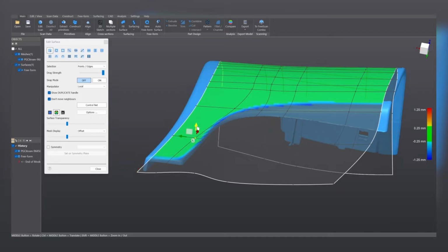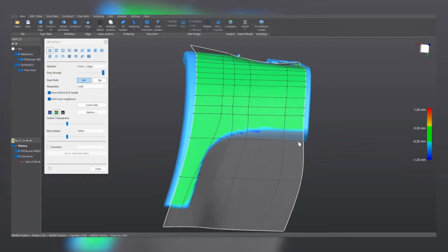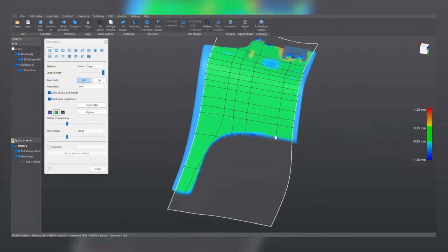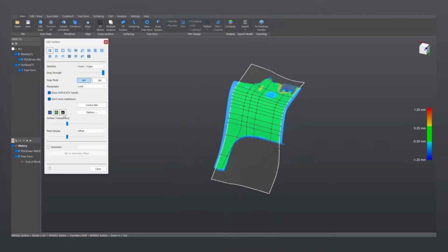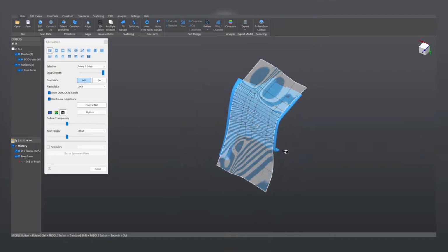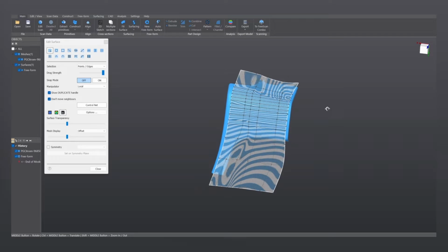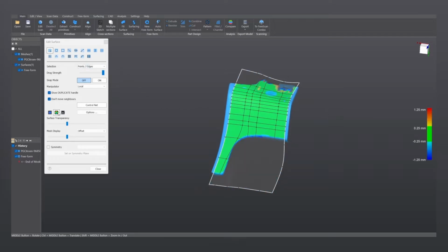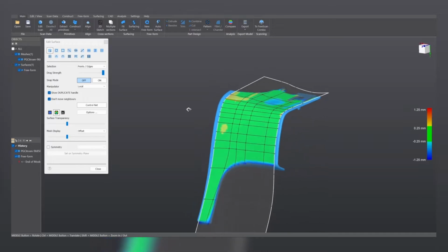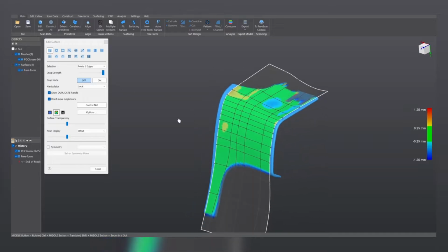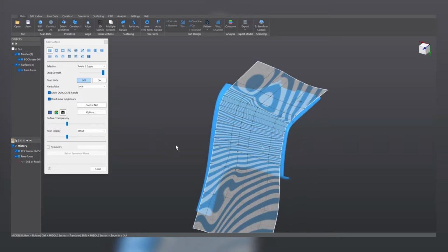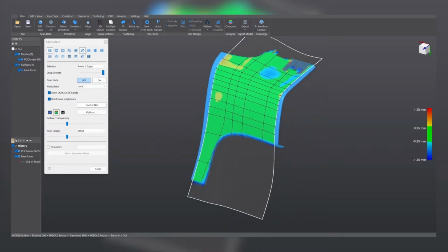Okay, I'm quite satisfied with the result now. Before continuing, the surface is adjusting quite well onto the mesh, but let's check the surface quality with the zebra stripes. What we have to pay attention to here is that these zebra stripes move smoothly onto the surface. To improve it, we can give it some clicks on the smooth tool, and by compromising the tolerance a little bit, we obtain a better surface quality. So with that, I believe we have obtained a really nice surface.